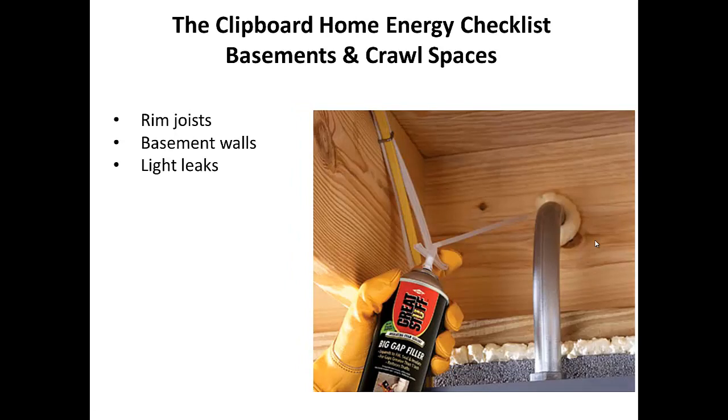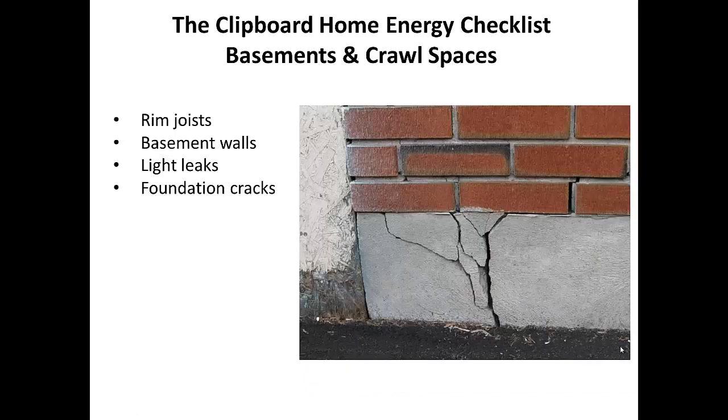If you're in your basement and you're looking at where utilities come in and you can actually see light through those holes, you really want to get in there and use some Great Stuff. And this is one of the cans that is available for homeowners at Home Depot or Lowe's or anywhere like that. Any hardware store will have this stuff, and you can see he's used it where this electrical conduit is penetrating, as well as where the sill plate, which is what this piece of wood is called, sits on the foundation here, and they've foamed the edge of that to stop air infiltration losses.